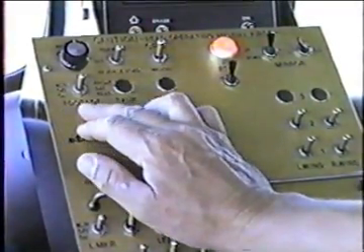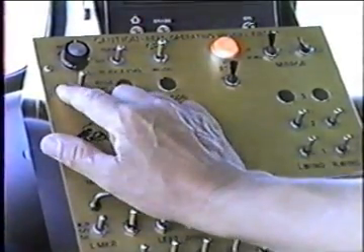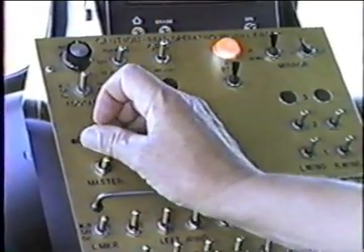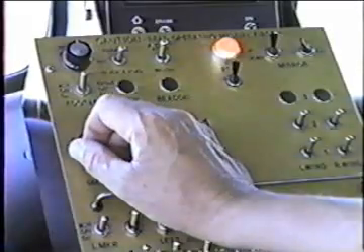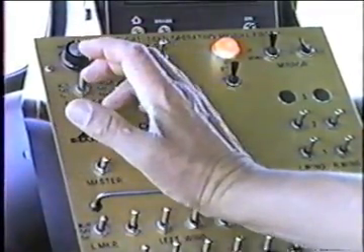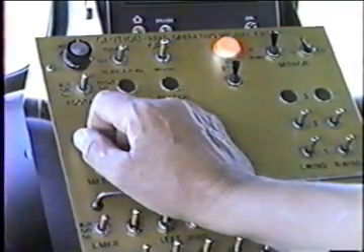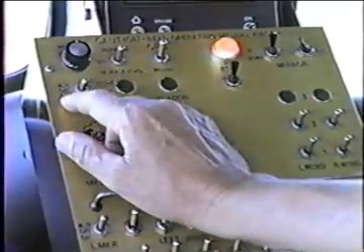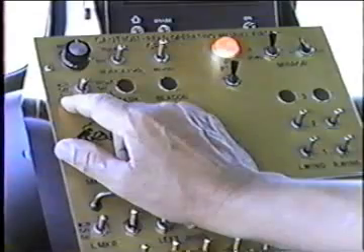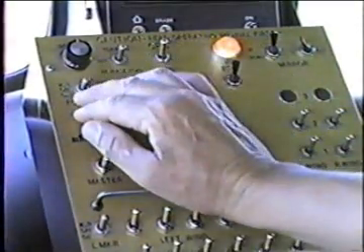Over here we've got a footage switch. The footage switch has 3 positions. It's got master. That means that anytime the switch is in the up position, whenever you turn the master switch on, the computer is going to measure the footage. Anytime you turn the master switch for the spray bar off, it'll quit measuring, so that this shows distance sprayed. Center off position. Down position, this turns the footage measurement on. If we want to measure a distance or check a speed, just flip that down and nothing else has effect on it.